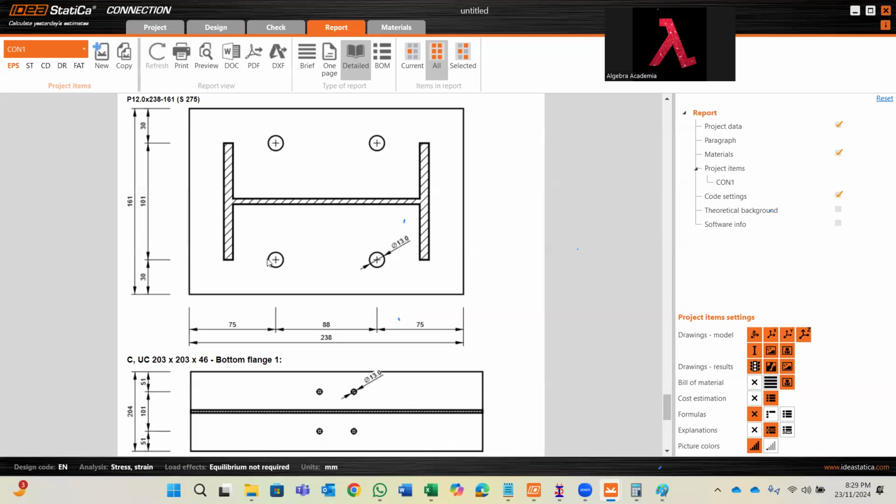in the cover side, because the minimum cover which you're going to provide in the pedestal is 50 millimeters, right? So I need to provide the anchor inside the reinforcement. So there it has concerns in the pedestal where you're going to place the edge distance, but here it doesn't matter. So minimum 30 to 40 millimeters is fine. Okay.